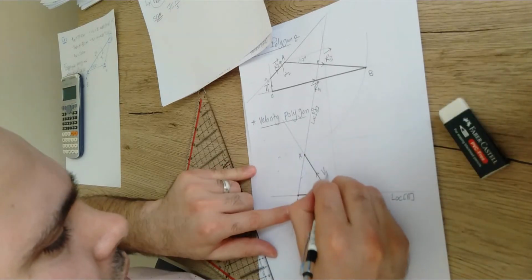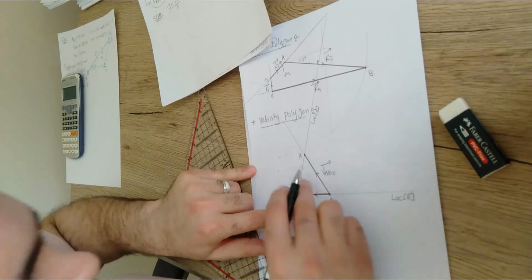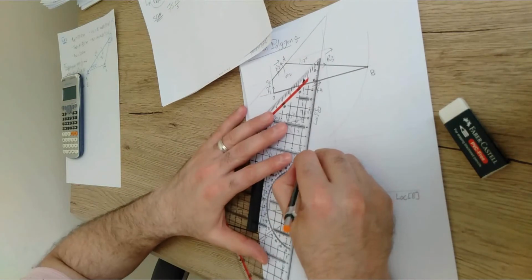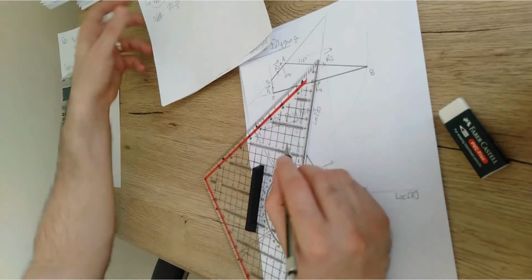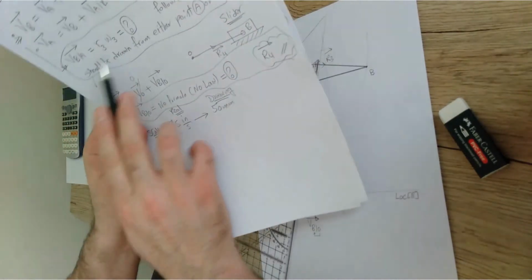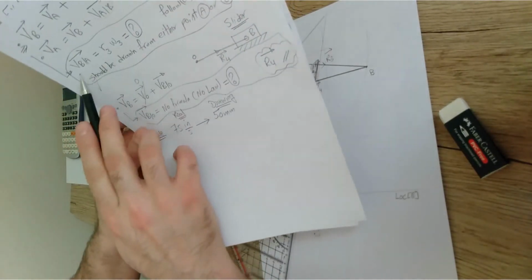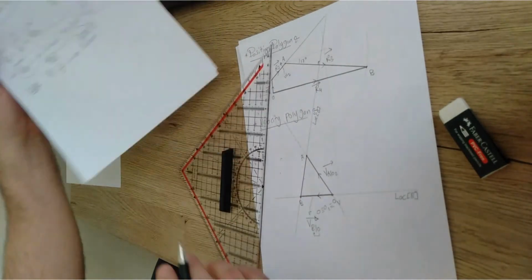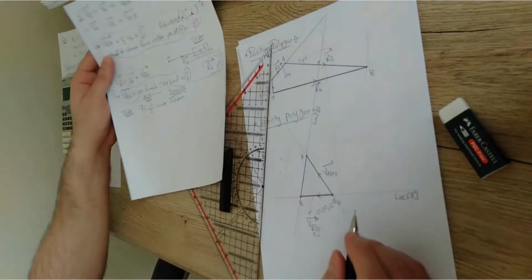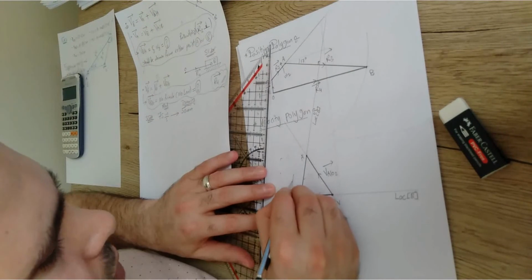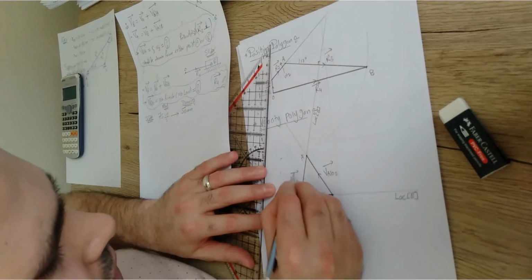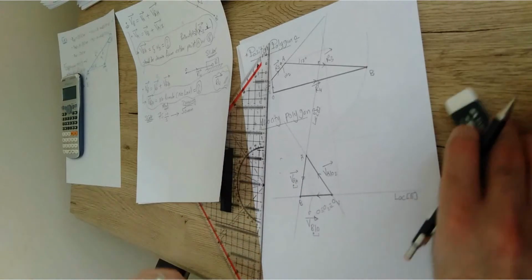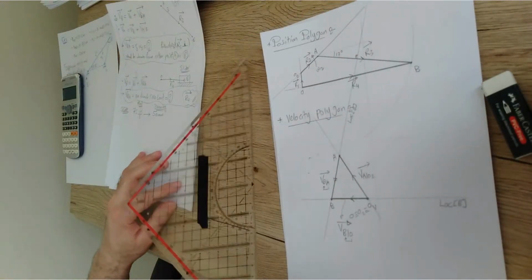Here, this is gonna be VA relative to O2 vector. This one I just wrote, this one belongs to this vector. Then I'm gonna connect A to B, because I need VB relative to A. So there should be a velocity vector set up between points A and B. So that's why I'm connecting these 2 points A and B. And the direction of this one is VB relative to A, means moving from A to B. This is the VB relative to A direction.